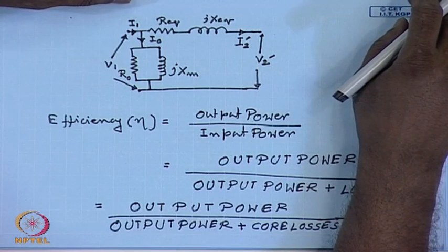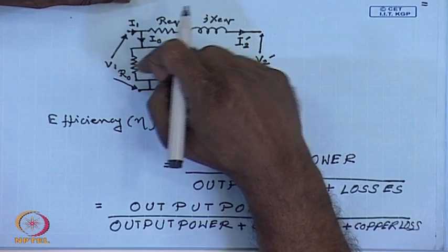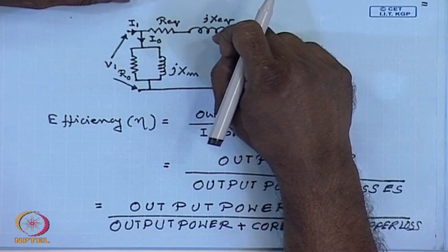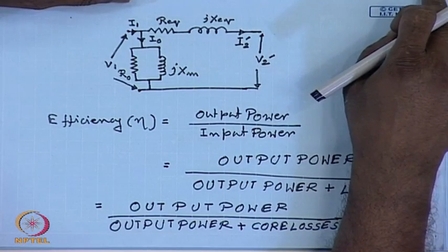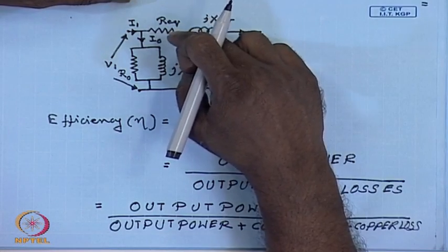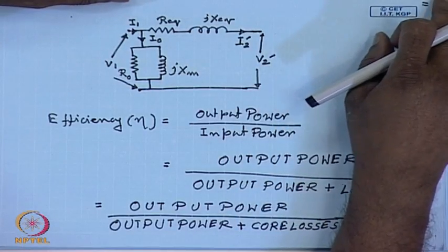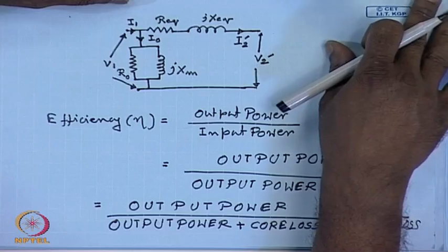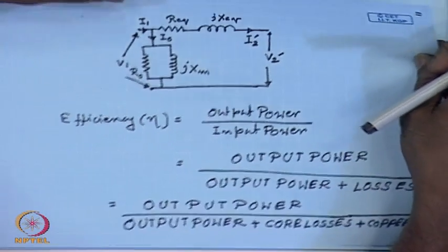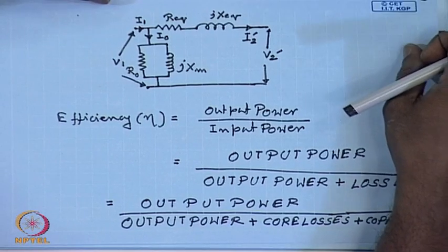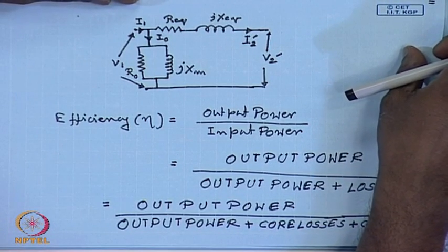Similarly, from the short circuit test data, we argued that the magnetizing current is very small, therefore, the core loss is very small. So, the wattmeter reading actually represented the copper loss. Now, short circuit test is usually done at the rated current, therefore, the value we get is the full load copper loss from the short circuit test. Similarly, from the open circuit test, we get the iron loss, which is independent of the load current and constant.